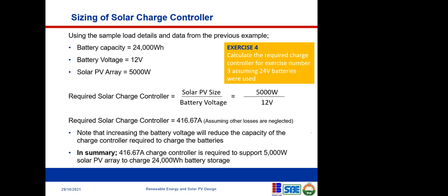So it means that I've already taken that into account for my solar panels and my battery bank. Just a thought about what you just asked: your charge controller is rated in amps, at a certain voltage, maybe 12 volts, and your batteries are rated in voltage and amp hours, right?